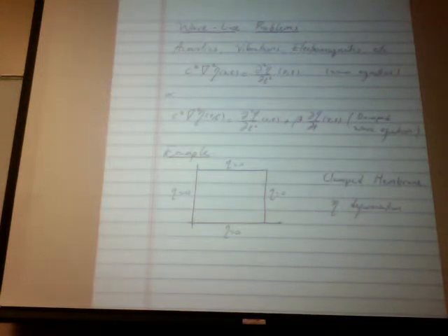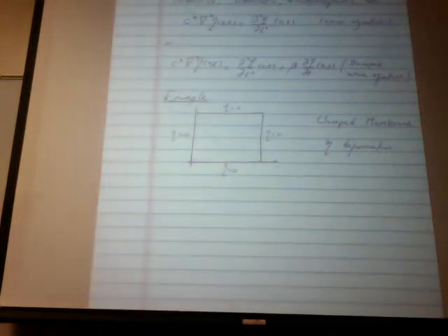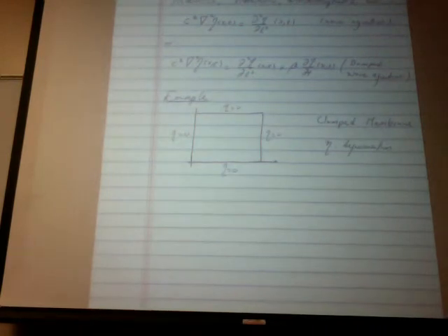Well, in the case of a drum, we have a circular one, so we'll have to use polar coordinate systems. But think of a square drum. Okay, you clamp it, and then depending on the characteristics of the material of which the drum membrane is made, it will vibrate at different frequencies and will produce a certain sound. In this case, eta is a deformation, essentially meaning the position with respect to a datum or a reference line as a function of time and space. It's 0 on the borders because it's clamped completely.